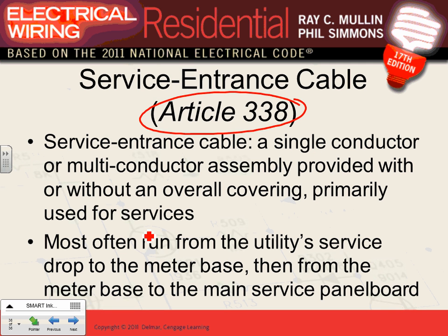That's the main application. If you have a multi-building setup, like on a farm, if you live on a farm and you have a pole in the middle of a yard, and you take a branch that will be a service conductor to each one of these structures, an SC cable would be your cable of choice in these applications. I wouldn't wire the whole house with an SC cable. It wouldn't be economical, though you can. That's basically a few things about SC cables.